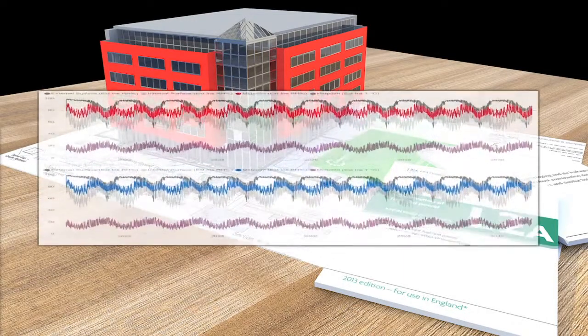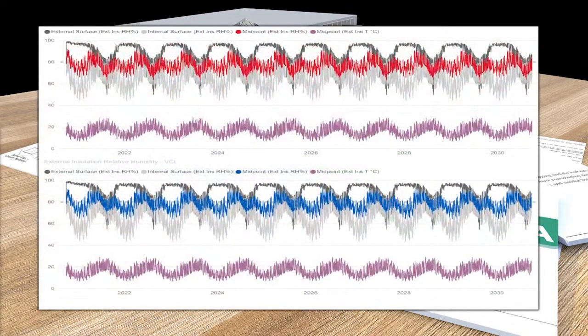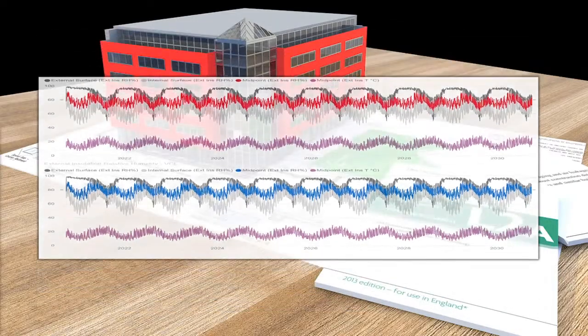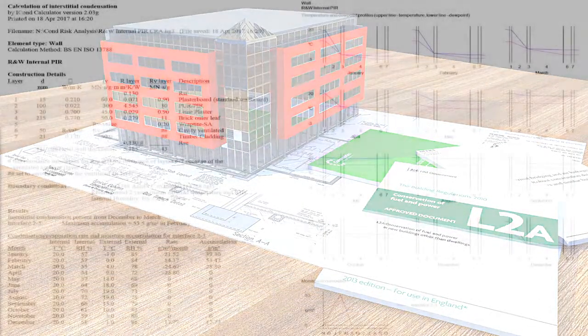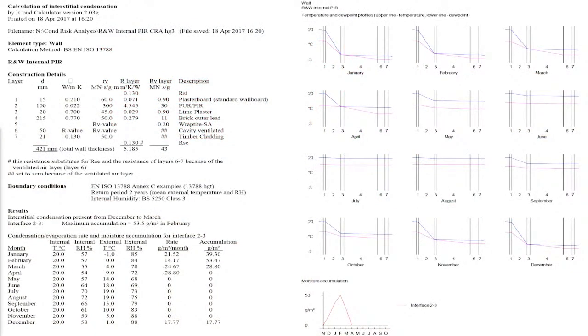In addition to fully modelling the energy performance, we must also make sure we properly assess how the building design balances moisture. Balance in this context meaning we must ensure that all moisture associated with the building can dry out, and that any moisture accumulation or wetting is balanced and equalled during the life of the building. As with energy modelling, it's important to use the right design tools.